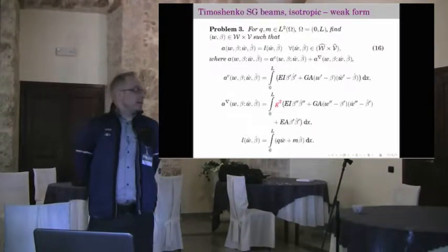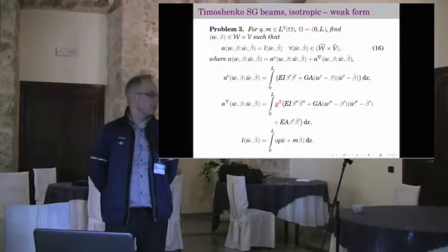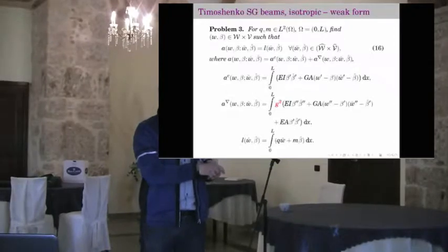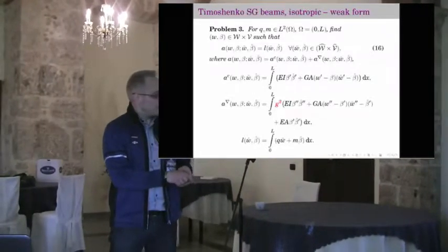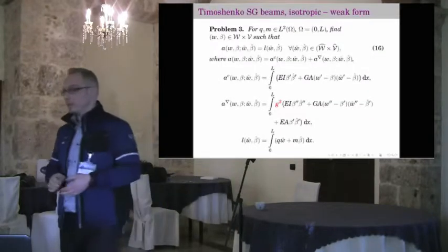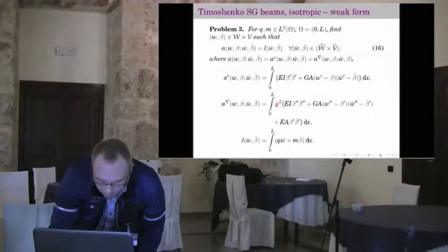Okay. And this is the Timoshenko problem, and everybody knows that in the classical Timoshenko problem we have the so-called locking problem, which is this term. But now we can see that in this case we also have an additional locking term here, just one derivative more. And this is of course from the numerical point of view quite important.